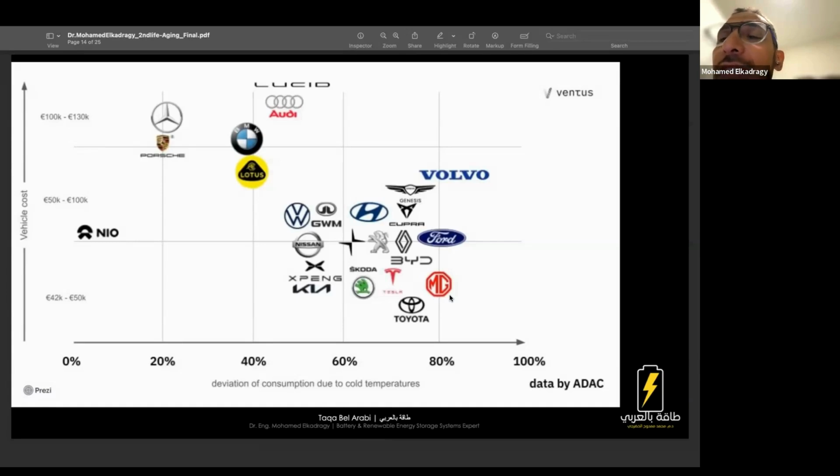They have done this test as well, exposing the battery to the range of operation. They have different aspects of testing different vehicles, but the main thing here is that we still have effects on battery performance in the market due to the use case. And we have to take this into consideration in aging and safety evaluation for the first life and, of course, for the second life. Next, please.